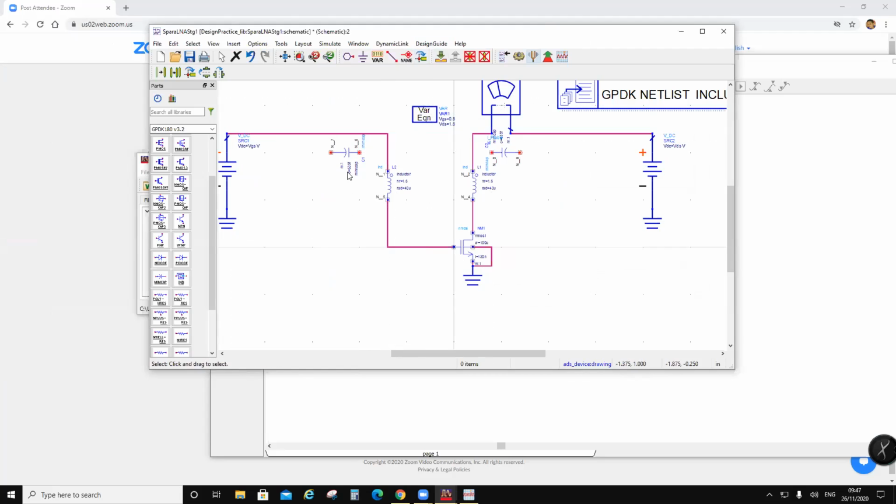Okay. And then, of course, now there is a basic difference between CMOS, SiGe, and GaAs and GaN. The problem is in CMOS and SiGe, we don't have a real ground, in the sense the ground is coming through bond wires, okay? Because there are no vias. Why? Because silicon and silicon germanium are electrically conductive.